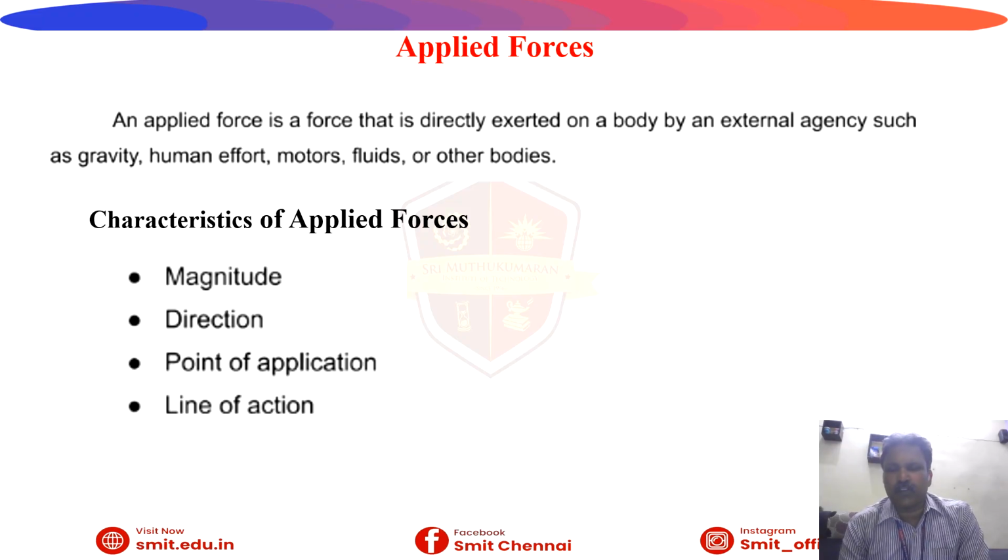Characteristics of applied forces, that you might already have studied in physics, are magnitude, direction, point of application, and line of action. Point of application means where we are going to apply the force. Line of action is the same line of path along which the force impact will be acting. That is one of the things, that is line of action.